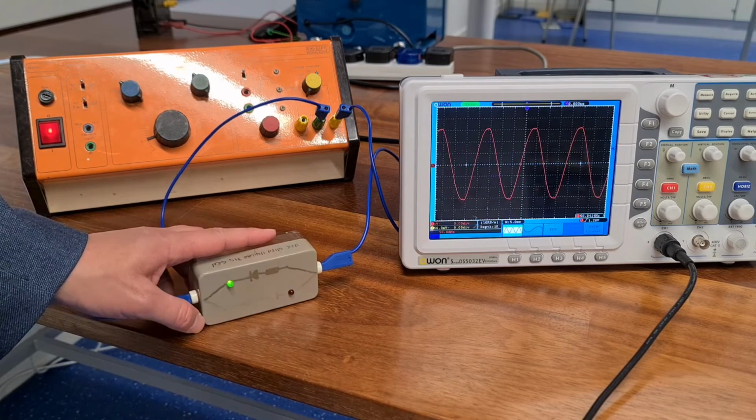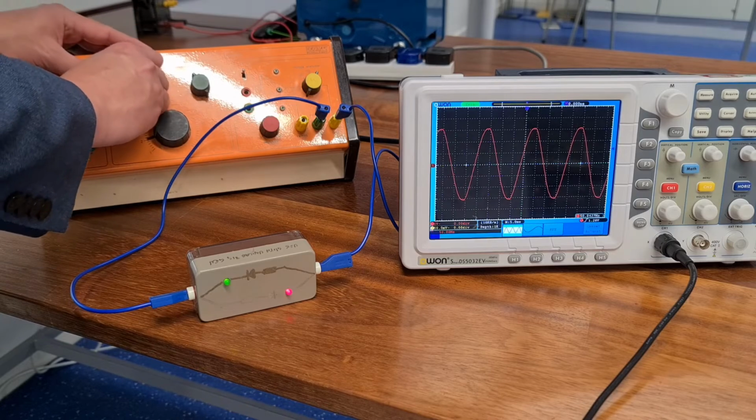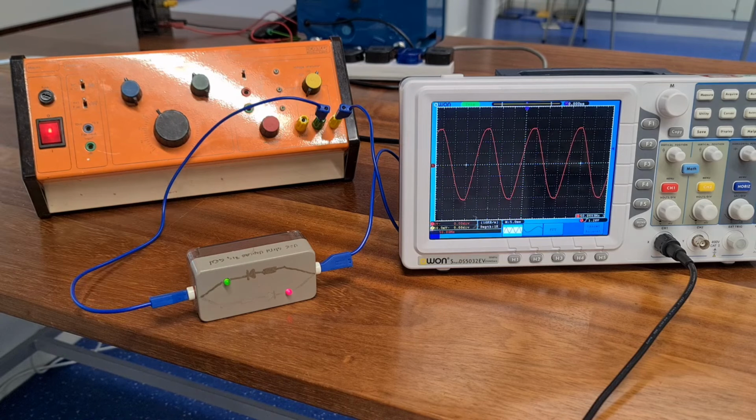Now, this is not the frequency of mains electricity. Mains electricity has a frequency of 50 Hertz, which means 50 times every single second the direction of the alternating potential changes. So I can set this to 50 Hertz. And now you can see that both LEDs look illuminated. But that's because they are flashing so fast that our eyes cannot see them. Let's have a look at them in slow motion, and hopefully we will see that they complete one whole cycle in 0.02 seconds.